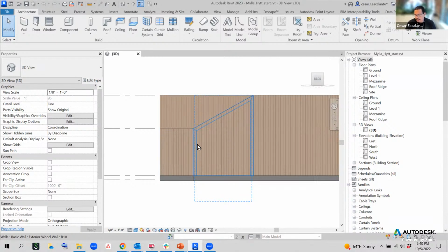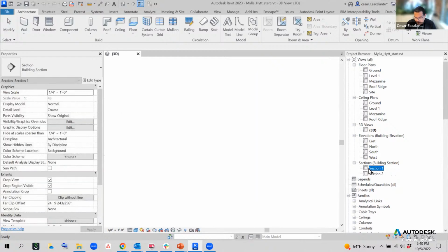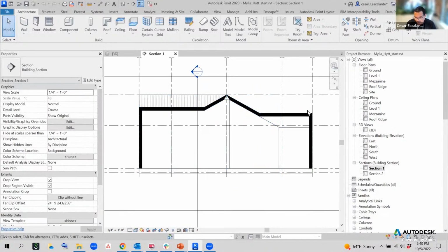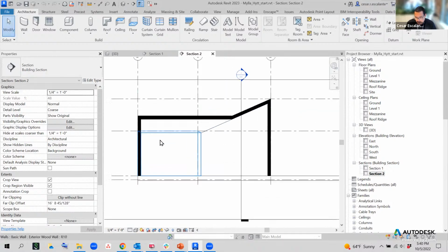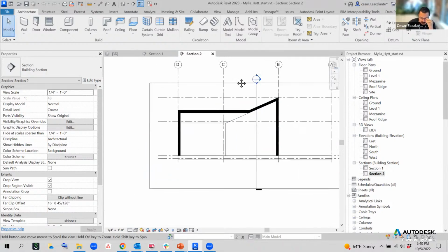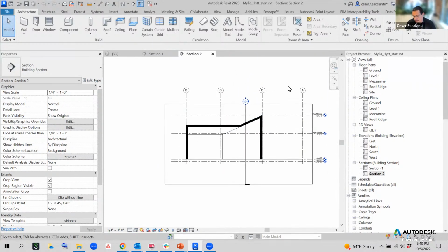I showed you the process of controlling the wall intersections. And because I used the same wall family for the roof, all the sections in the project came very clean. And they display a very sharp line weight, which is sort of ready for this type of presentation style.